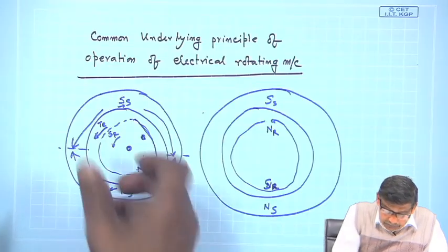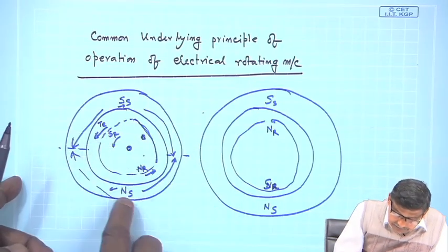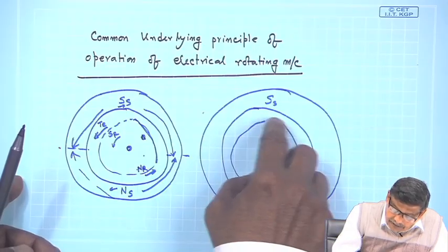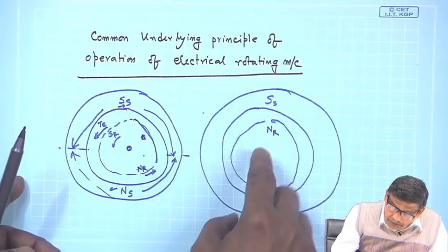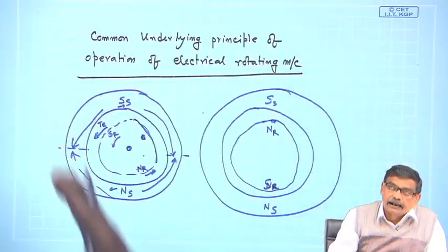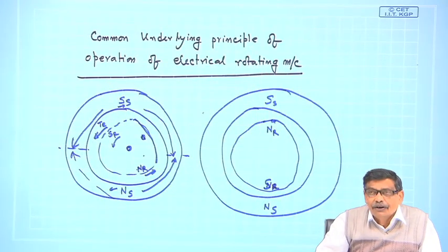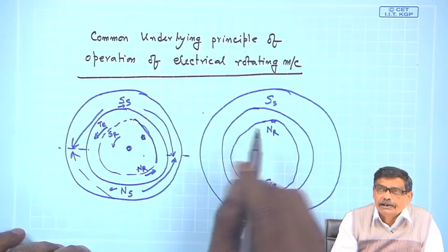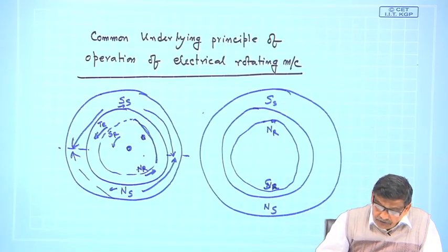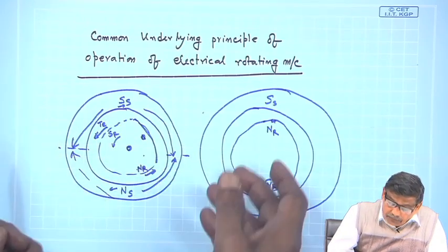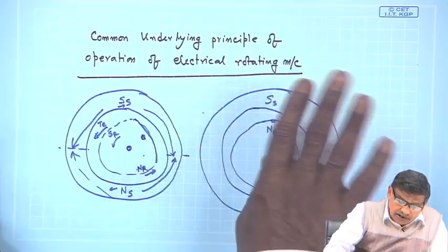And when they are aligned, as it is moving, SR is coming under NS. So like this it has come here, and at this point you can easily see that when the stator and rotor fields are aligned along the same line, there is no torque, nothing like tangential force it will be experiencing. So we first note that for this torque, the game will be over soon.